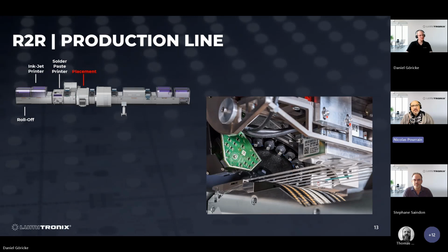After the solder paste, like in a regular SMT equipment line, you have the pick and place. This pick and place is very specific high-speed equipment for the LED, for the connector or specific IC, and it can go up to 50 to 500 components per hour.